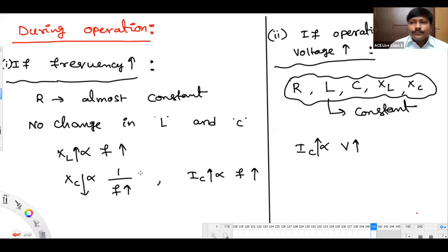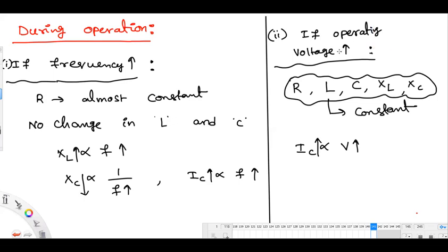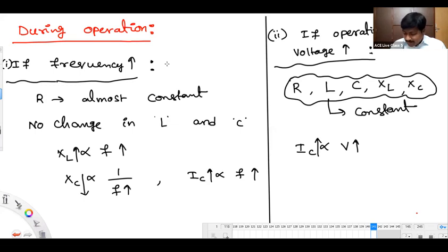Ramakrishna. Yeah, hello, good morning, sir. Good morning, Ramakrishna. Tell me. Sir, these capacitance values are much small now, so will they make any large changes in the system parameters of voltage? Definitely, it will change. Charging current will change. In a general transmission line, if the length of the line is very high, definitely it's going to show a large effect. For short length of lines, it may not show a great effect, as you said. For long lines and medium lengths of lines, definitely it will show the effect.